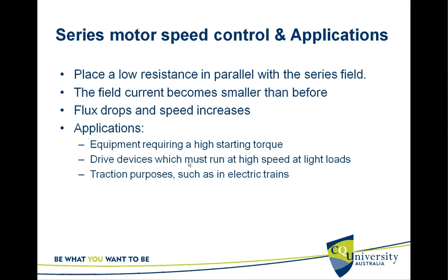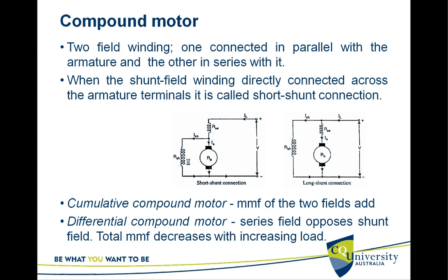Applications: any equipment requiring high starting torque, or drive devices which must run at high speed at light loads, or traction purposes such as electric trains. This is good. And the compound motor.